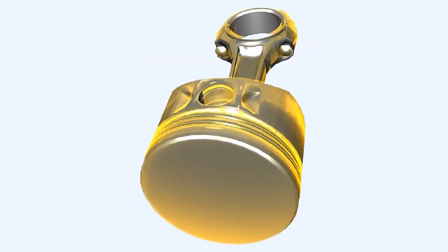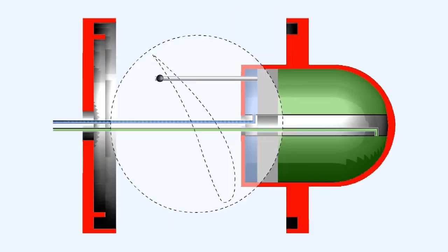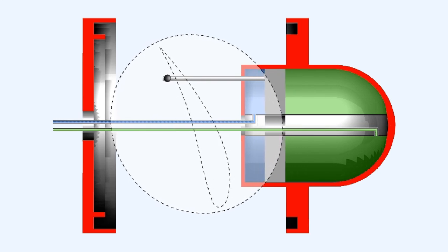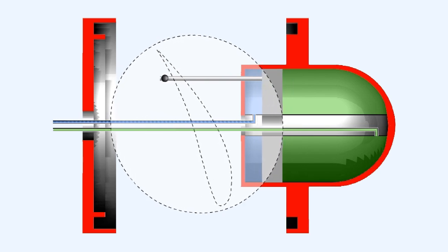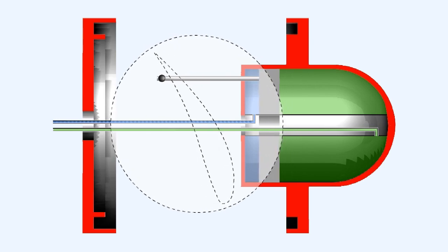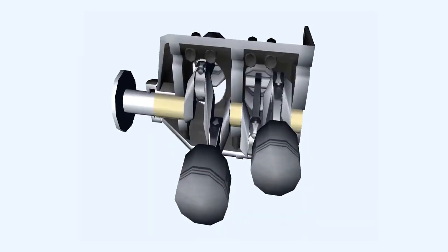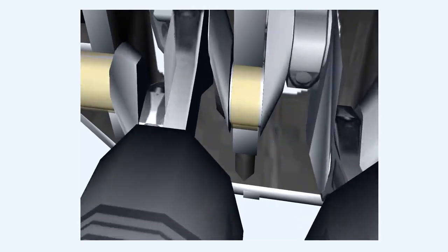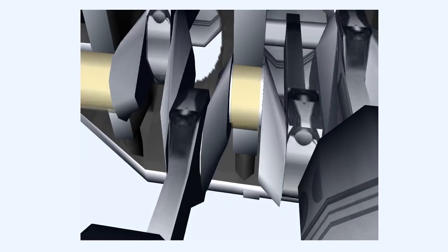The internal metal components are protected against corrosion by the lubricant, particularly if it contains a proportion of fatty oil, a thin film of which tends to stick to the metal surfaces. The oil can act as a hydraulic medium in 2 ways. Firstly, it can provide the power source for the operation of various components on the engine, such as variable pitch propellers. Secondly, it also acts as a hydraulic medium by reducing the shock loading between the shafts and bearings in the engine, thus reducing vibration.